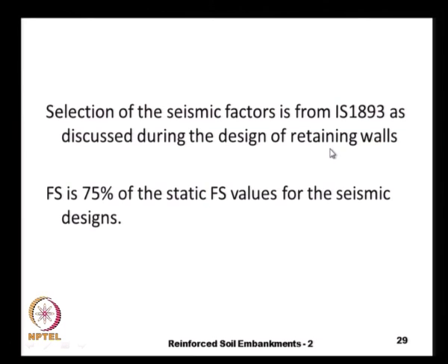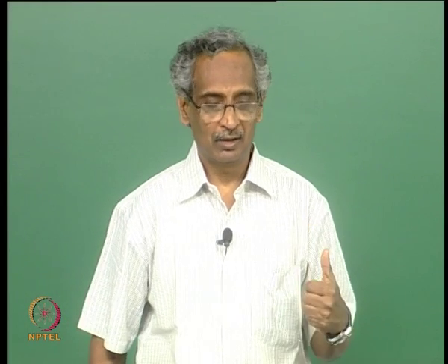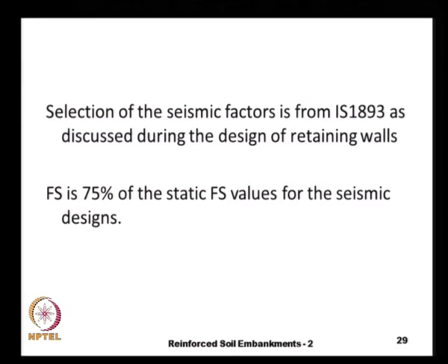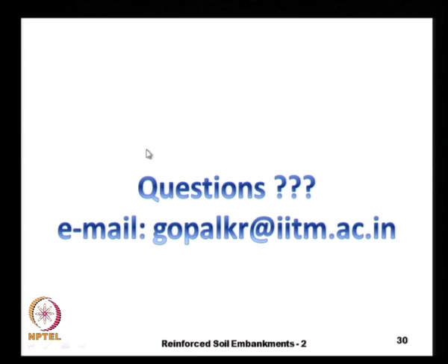The same principles apply even for this case, and when we consider the seismic forces, our factors of safety can be reduced to 75% of the static values, as we discussed earlier. So, for example, if we need a factor of safety of 1.5 under the static case, under the seismic case it can be 1.125.